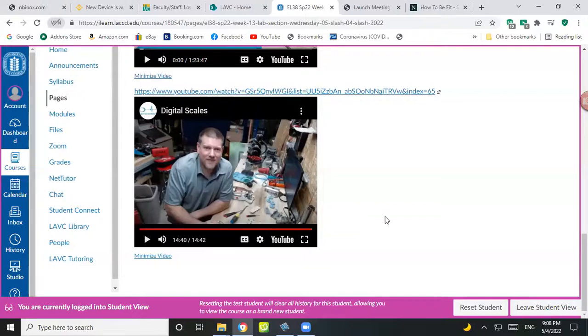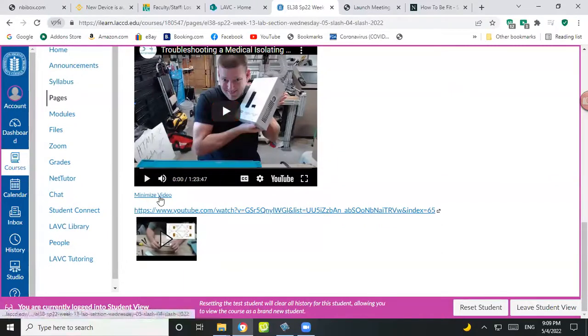Okay, so that's something for newer guys in the field: make sure to look for the manuals before you take it apart. Don't start taking the whole thing apart. Sometimes it might be very, very simple troubleshooting, and you probably don't need to take the whole thing apart, right? From looking up the troubleshooting chart, you might find that they ask you to do something like a hard or cold start or a reset process, because something might have locked up in the processor. That could be something very simple to follow. Okay, all right.